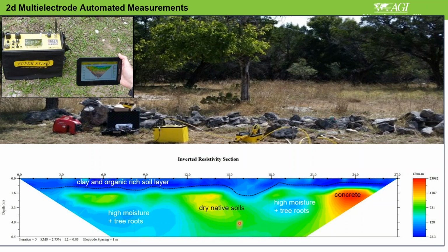So what you may get, for example, when I do 1D electrical sounding, everything will be blue at the top, the same depth interval. You cannot get this variation of depth interval. You will get the same depth. The second layer on the 1D electrical sounding will be a more resistive, a little bit like yellow and green. So that means you really will not see these variations.